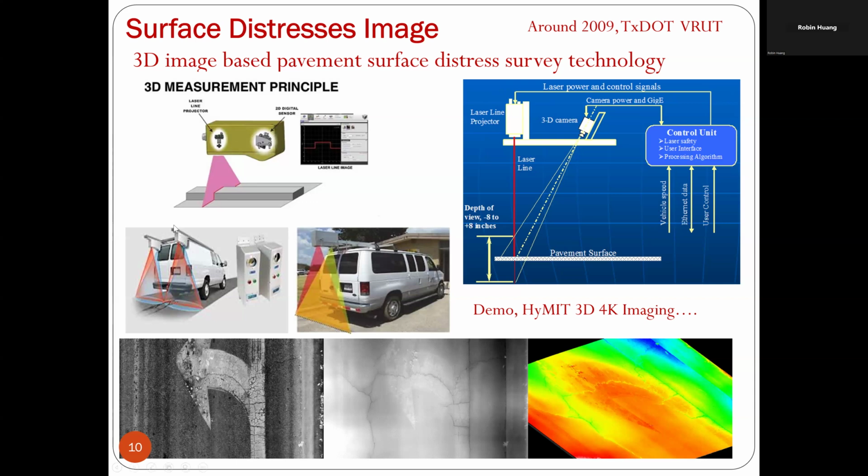The basic technology here is you see this is the laser line, the line projected to the ground, and the camera sees it from an angle. In the image here, you see the square. The laser image will change shape in the camera image. The shape size is roughly related to the object height. This technology is very popular in transportation inspection. People use a laser camera to grab the 3D picture from the surface. This technology is called laser triangulation.